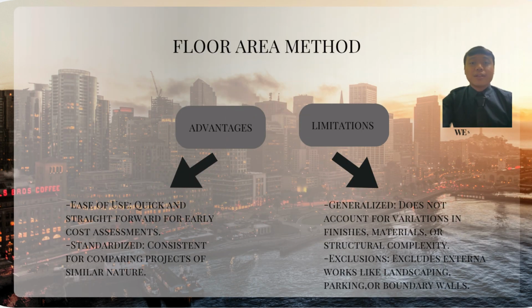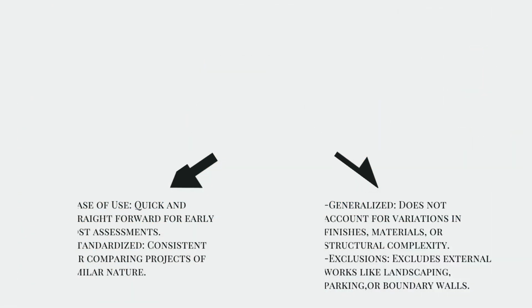Number 2, floor area method. Advantages: ease of use, quick and straightforward for early cost assessment. Standardized, consistent for comparing projects of similar nature. Limitation: generalized, does not account for variation in finishes, materials, or structure complexity. Exclusion: excludes external work like landscaping, parking, and roadway walls.